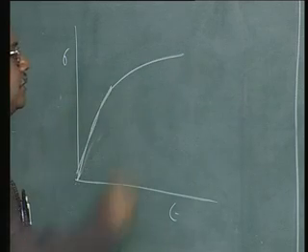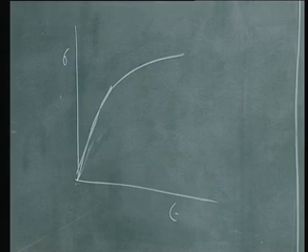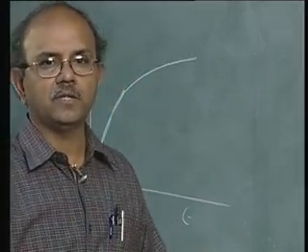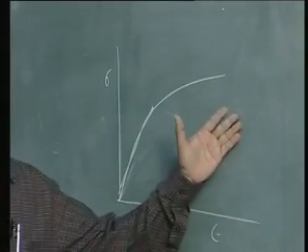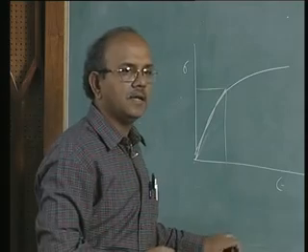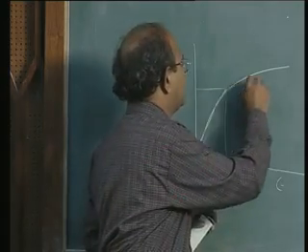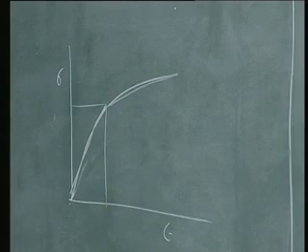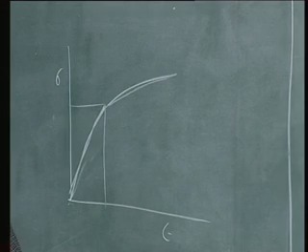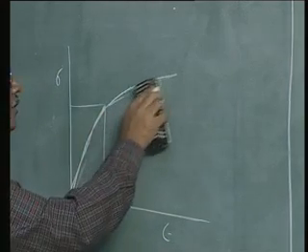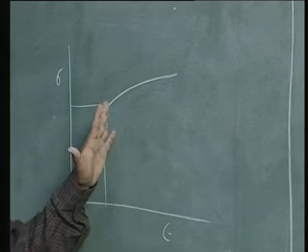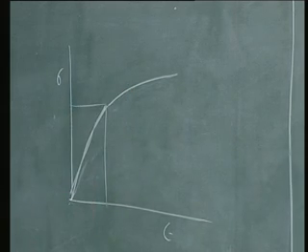So this would be the stress strain curve. Most of the times, basically because it's easier to understand, this would also be treated as a bilinear system, or in other words, with sigma y as the yield, the elastic part here may also be treated as a linear part. Anyway, it doesn't matter whether you treat it as a bilinear system or as a linear followed by a nonlinear system.